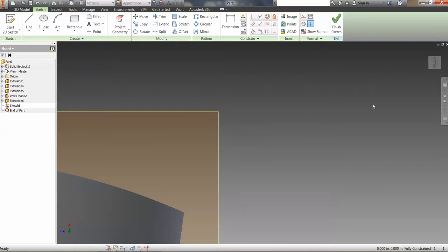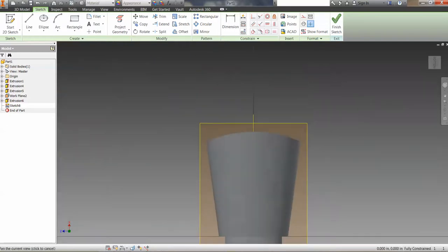Now, again, there's not exact dimensions on this, so you get to sort of make the head look however you want, tall, short, skinny, fat. It's up to you. What I'm going to do is start below my work axis here, try and center that, and go straight up. And this is how I get to decide how tall it is. It's already down inside the body a little bit, so that will work out good in my opinion. And then this is the axis that the head is going to revolve around when we draw this out.